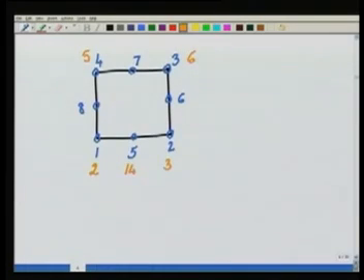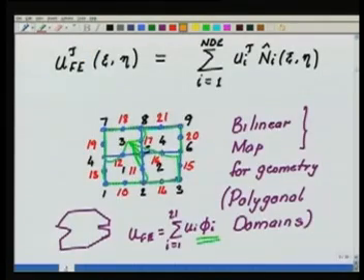So it is 14, 15, 16, 11. Okay, note one more thing: what I did first is I went ahead and numbered these corner degrees of freedom, then I started looping over each element, and I started numbering for the first element all its side degrees of freedom. I am giving them global numbers. So first I had the 9, then I added 10, 11, 12, 13.